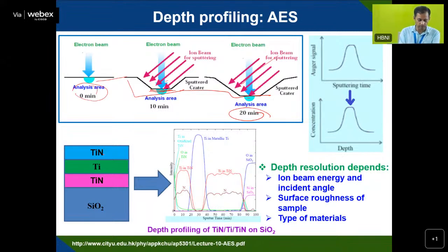From the element analysis, you can see here a SiO2 substrate, and titanium nitride is a layer by layer structure. On this SiO2 substrate the titanium nitride is grown, and you can see, like the XPS data here, on the top surface you have nitrogen, then going deeper there is no nitrogen, again in this layer there is nitrogen, and then in the depth profiling there is no nitrogen.